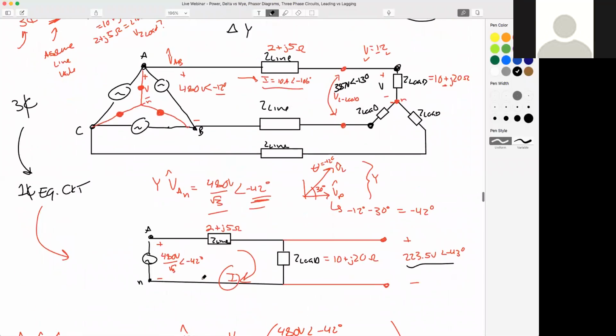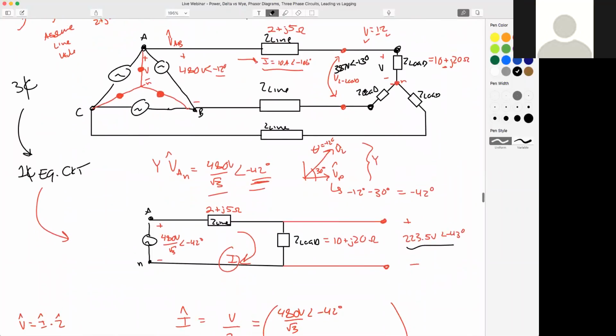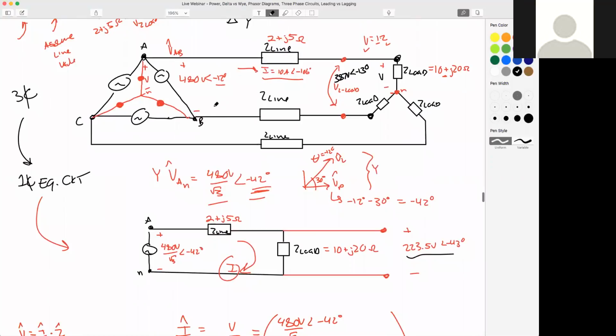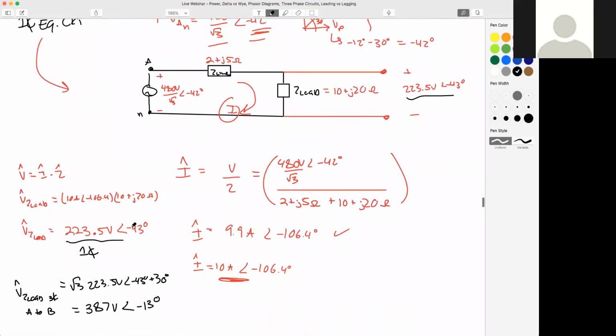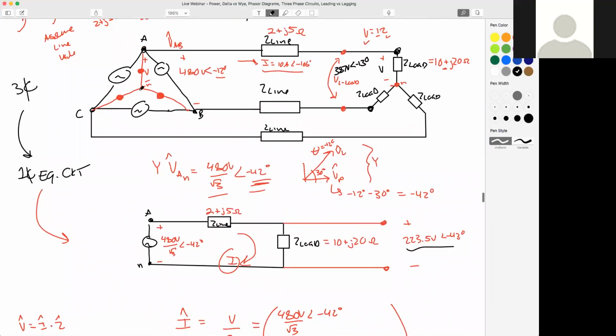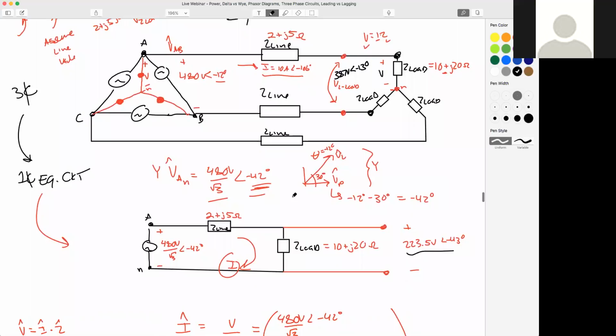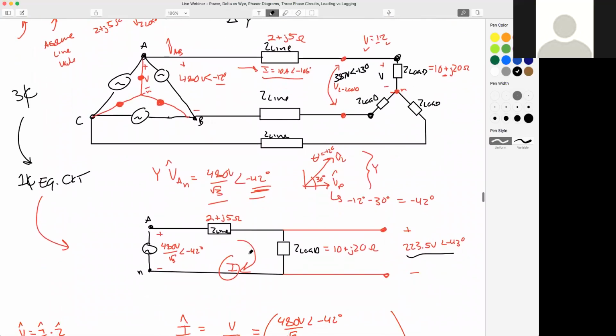So we did a line to phase voltage transformation and then a phase to line voltage transformation. Is everyone good with that? Does everyone see why we subtracted 30 degrees to get to the equivalent circuit, and then why we added 30 degrees to get to our line voltage? Is everyone good why we modeled a Y source even though we were working with a delta source to find that current? Good. Eric said, can you discuss the negative 30 and then the 30?